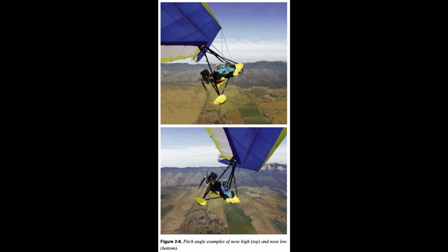Pitch angle is the angle the WSC wing root chord, center of wing, makes with the Earth's horizontal plane. Many pilots confuse the pitch angle, which is easily seen and felt, with the angle of attack, AOA, which is not as perceptible. For example, if flying in a glide with the engine idle and the nose lowered, the pitch angle can be below the horizon.